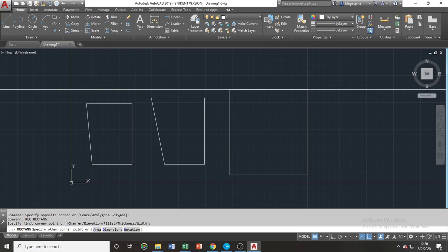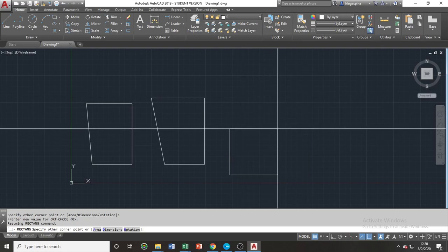So the first method is the direct method without choosing any sub option. In order to put our dimension, we will type first the @ symbol or shift 2 on our keyboard, and then type the desired dimension.